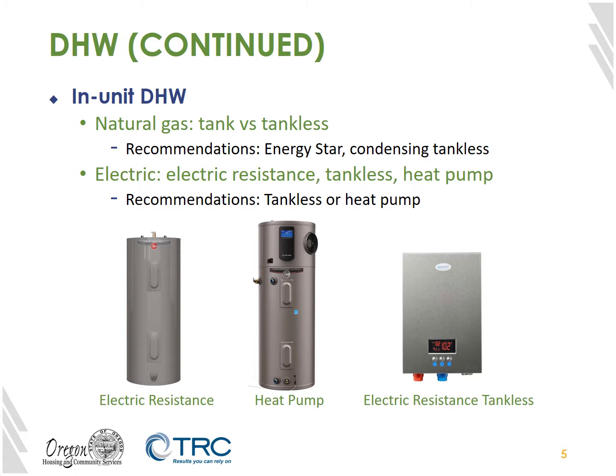Tankless water heaters do not need to keep a reservoir of heated water and so can be much more efficient in units where hot water is only called for rarely. However, because they must deliver hot water on demand, they require a breaker that can handle the high load. In buildings where natural gas water heaters are installed in the units, an Energy Star or tankless water heater may be viable, efficient options. As with electric tankless water heaters, gas tankless water heaters have high load requirements and so will often require a larger gas line than what was previously installed.